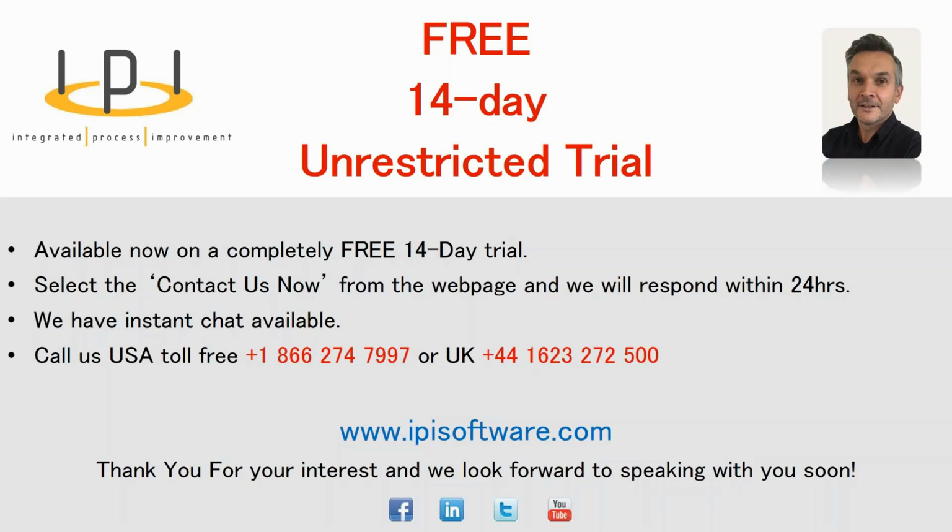You've probably seen from previous webinars, if you've been in attendance, the creation of the operation number, breaking that operation down into process steps. The process step then forms a logical next branch of being the characteristic. Characteristic then, how can it go wrong? What's a potential failure mode? And from the potential failure mode, you would assess your occurrence, your severity, and then finally your detection. So they're all branches that link together, and ultimately they all link back to the feature number. So yep, that one is good.